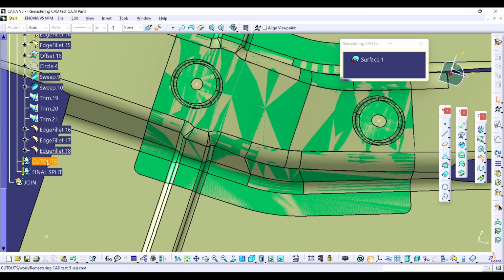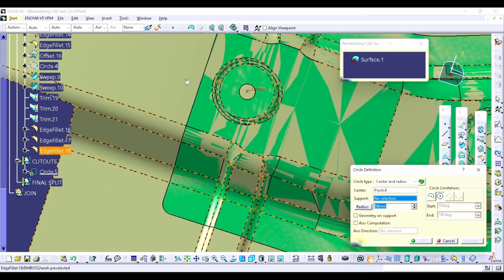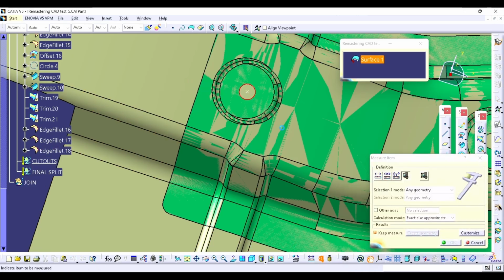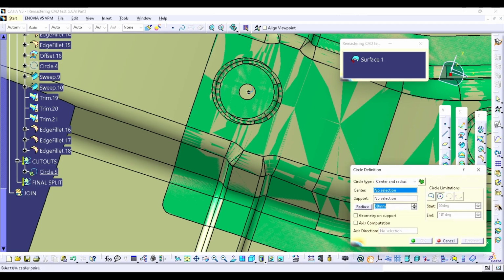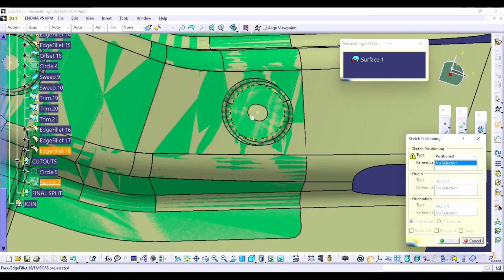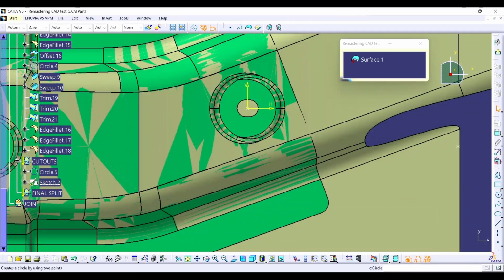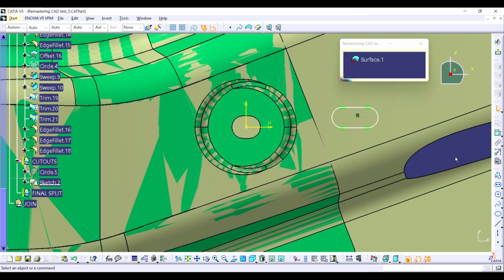Now we have to define the cutout, provide the cutout over here, select the point. Array, I haven't measured, so let's measure. Great. So go to the circle, provide the circle with 8 radius. It's done. For here I'm going to use the sketch because sketch is the simplest method to create an oblong hole. Okay, vertical, yes, done. So here we go to the oblong hole, just create one, put it here, delete this distance. Now go to the constraints, coincidence. I haven't done it properly, so let's do it again.